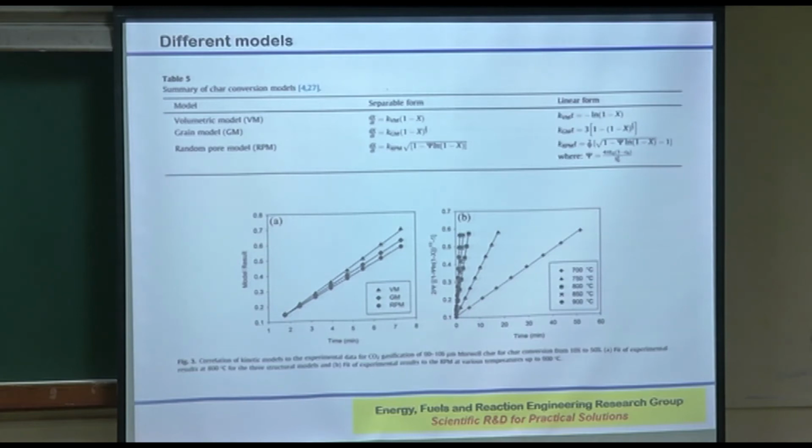Why does it work well? Because for some coals, the structure changes over time, and that affects the gasification reactivity. From very reactive to less reactive to completely unreactive, as I mentioned before, that is captured by that structural parameter, which describes the variation in the development of the structure.